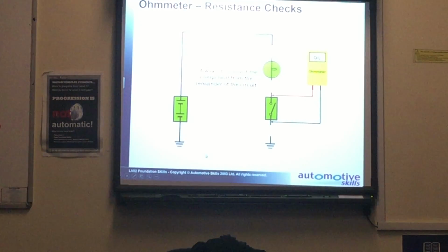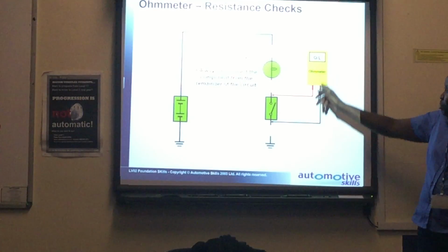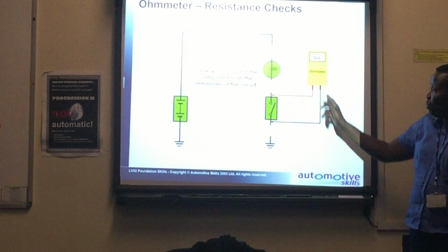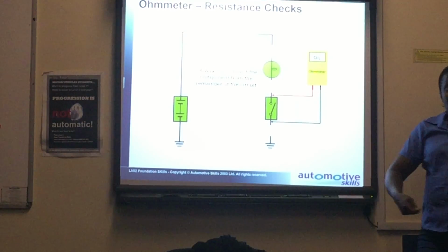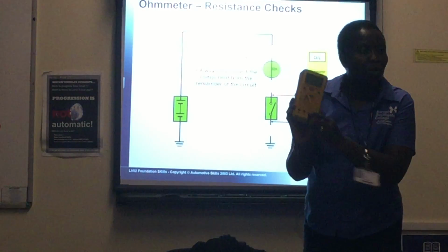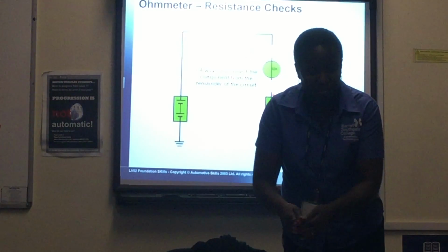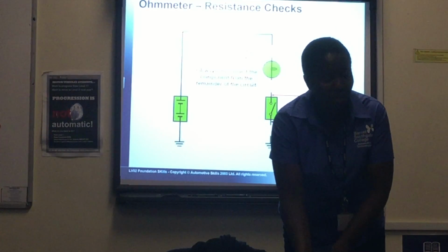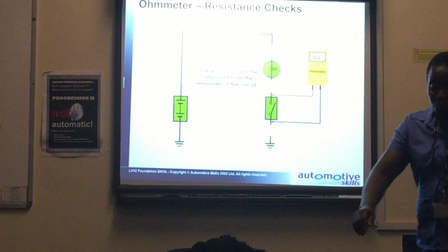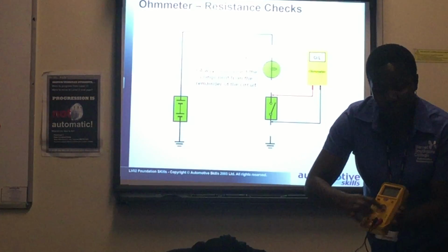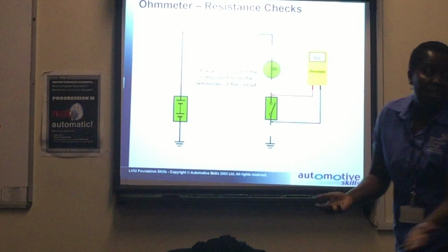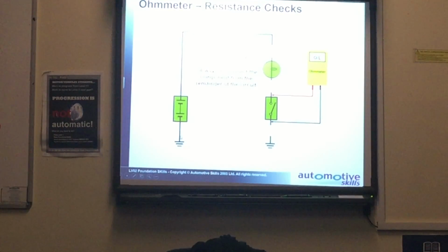We can measure resistance across the switch. Same thing, positive from where the current is coming from, negative, then like this. On the ohmmeter, this on the common, then this on the ohmmeter port. Then we just indicate a reading. This will be on. We have to set the dial to the ohm, where the ohm is. Then we get a reading. Nice. I have this on your handout as well. So you close the switch, then you can measure the resistance.